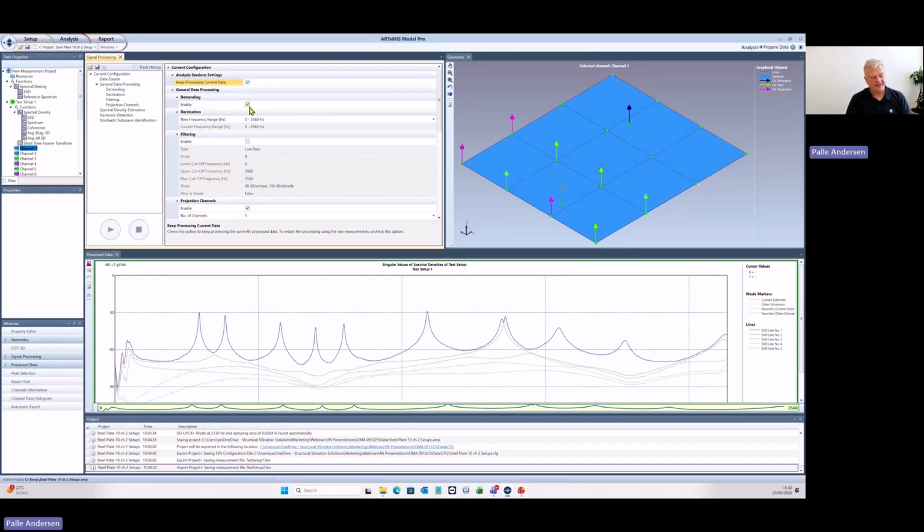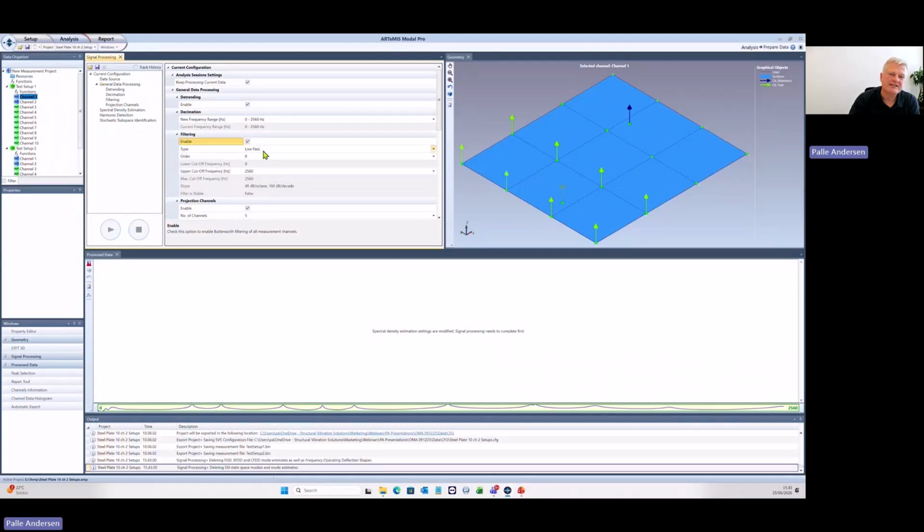If the trend is not linear, let's say it's a kind of growing, so it's growing up in some way, then the way to remove that is to actually introduce a filter. So in that case, you would have to click on this one here, and then you will have to select a high pass filter. And then you need to select an order. I normally use a very low order filter. I do not need a lot of slope in this filter here. I just need a little bit that can cut away everything that is around 0.